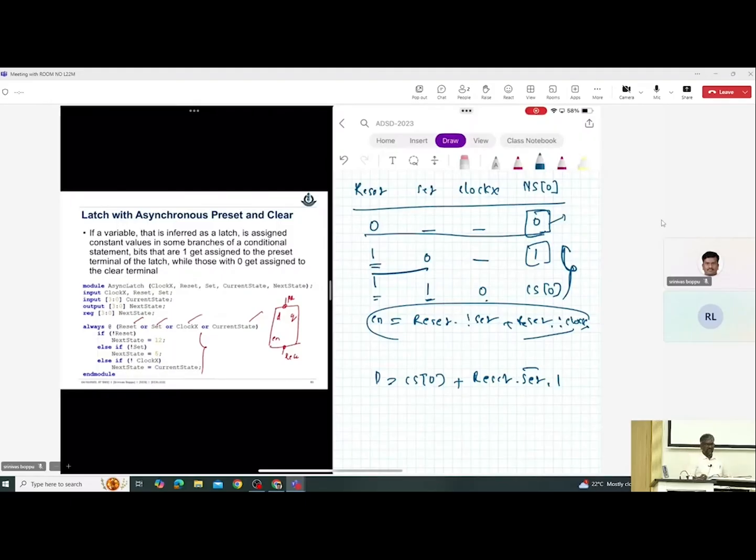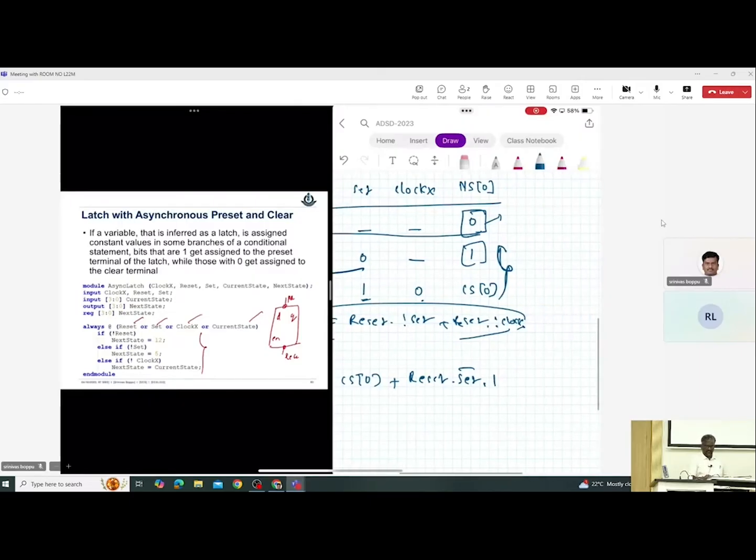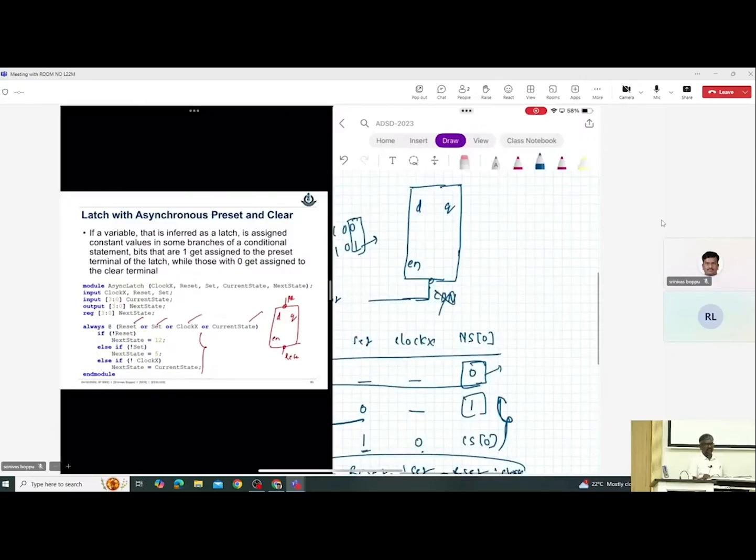In this case we have active low clear. What is the guarantee that we have a latch with CDN? Now I have a latch with only the CD signal, which is active high. What should I do? Just negate the logic: instead of connecting the reset, you connect not reset. Is that clear? Okay.